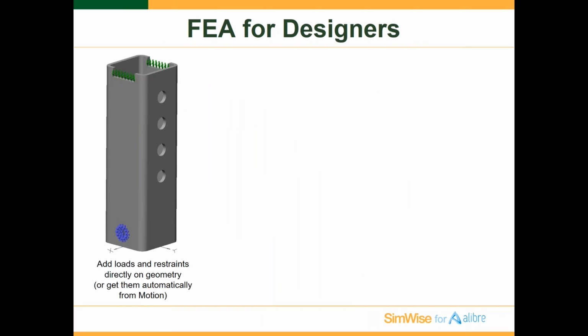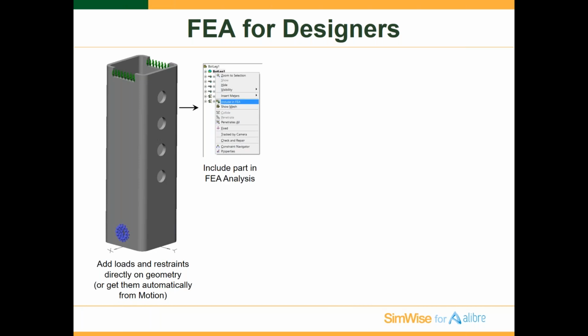Now, SimWise FEA is truly designed to be finite element analysis for designers. So we're trying to make it so that you don't need to be a specialist in finite element analysis to get good results out of a finite element analysis. So one of the things we've done is we allow you to add loads and restraints directly onto the geometry. So you don't need to worry about the finite element analysis mesh.